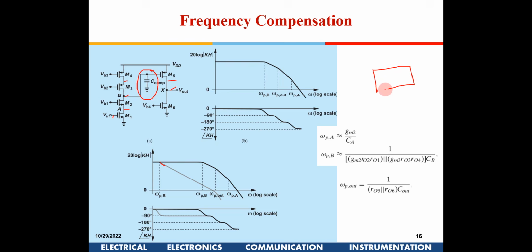The way a gate is fabricated, there will be a metal layer, there will be an insulator, and there will be a channel. In the channel towards the end, there will be some high doping, and they will take out the terminals. So you will fabricate capacitances like this: metal separated by insulator, and then a highly doped channel here. So capacitances are very common, and resistances are also fabricated.